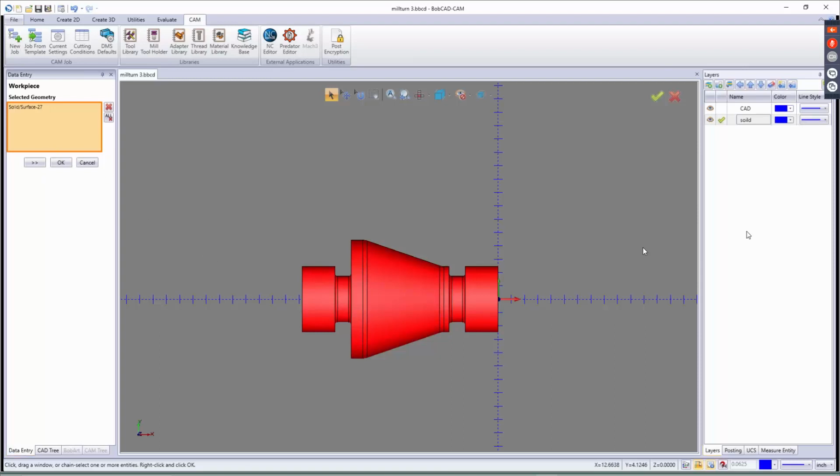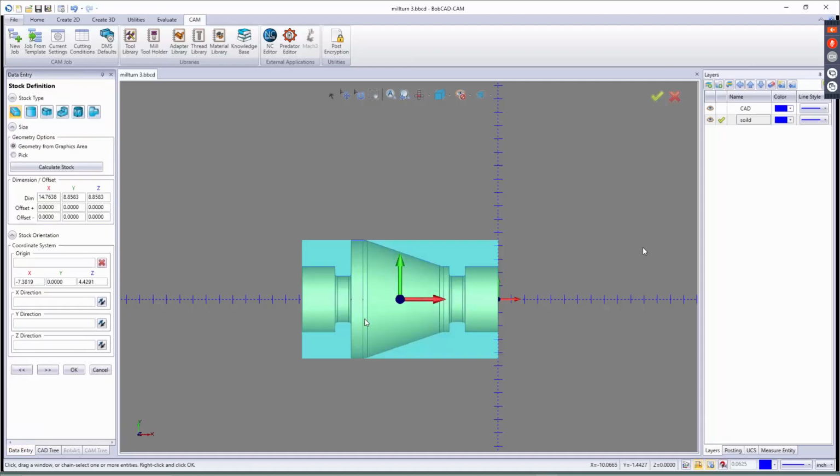I'm going to go ahead and select it this time, just because I know it's only going to be lathe parts that we do on this one. So we're just going to show the 2D geometry, and I'll totally forget about bringing in the workpiece if I want to. And you can use it as a cross-reference also in here. So from here, we'll go ahead and hit the arrows pointing to the right. And this brings up our stock definition.